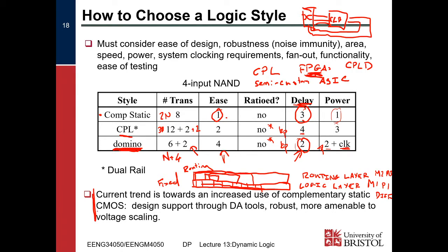Generally, in industry, the current trend is towards more CMOS usage. In the past, dynamic logic used to be key for microprocessors, and you had pass transistor logic and all sorts for discrete logic and sensors and things like that. The current trend is to just use CMOS because it's so much easier to develop. When you've got a chip with 5 billion transistors on it, trying to fix all the parasitic capacitances and determine the timing issues and glitches with domino logic is really quite difficult.